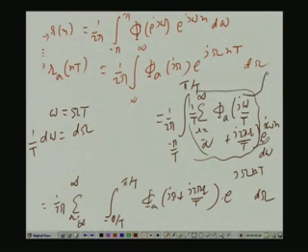This quantity will give you this, if you compare the two integrals. And the limits, sorry, I made a mistake, the limits will not be from minus pi by 2 t, they will be from minus pi to pi, because if capital omega is pi by t, the product is pi, and if capital omega is minus pi by t, the product is minus pi. So, integral limits are from minus pi to pi. Okay. So, you see the two integrals are identical. So, you can easily find out what is phi e to the power j omega. Okay, and the relation between analog and digital frequencies is small omega equal to capital omega t.